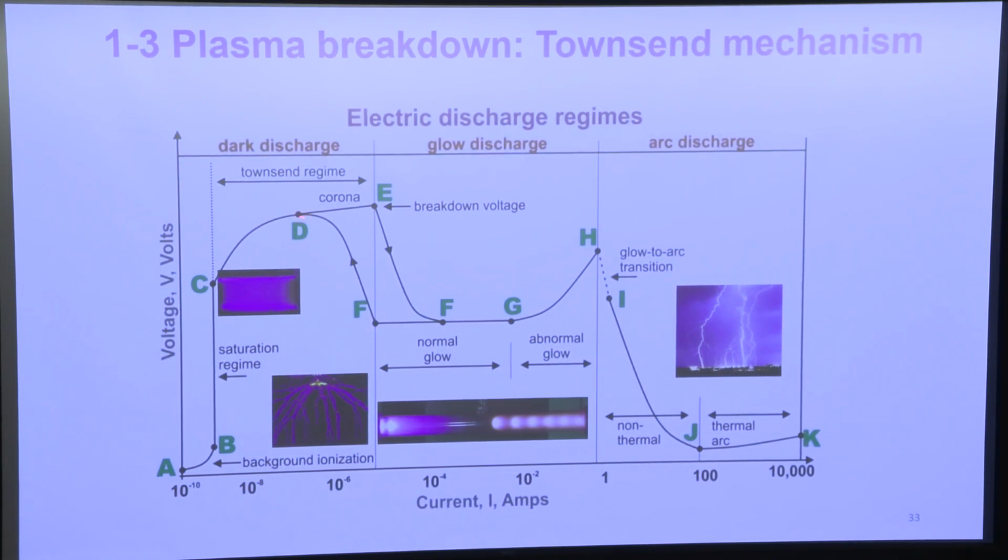So this is called corona. They generate this kind of streamer. We'll talk about what a streamer is and how it is generated. And then this streamer will die at the far field because there's not enough electrical field for it to continue. Just like a flame propagating into the mixture, and then the surrounding mixture is very cold or diluted, it dies. And then after that, if you continue to increase the voltage, suddenly you generate the glow discharge.